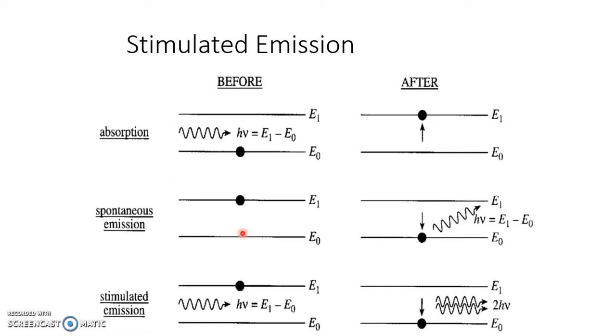So, in a semiconductor laser, population inversion is a must for lasing action or for maximum amplification of light. For population inversion to take place, it is injected by electrons. You inject electrons into the material at the device contacts to fill the lower energy states of the conduction band. And this is done by a process called pumping.